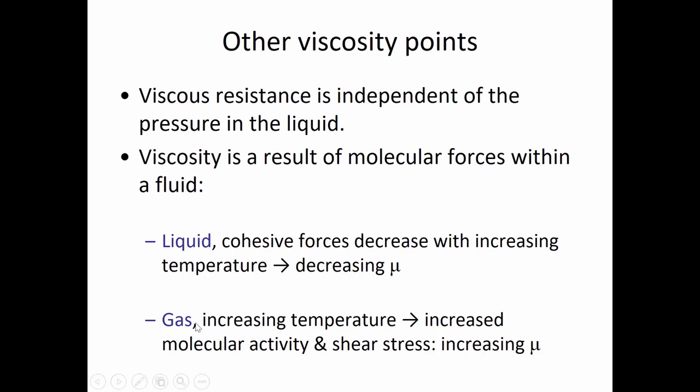In the case of a gas, because the molecules are bumping into each other, they have a lot more collisions, and the velocity of those collisions is higher. The gas molecules are getting in the way slightly more, and so the viscous resistance is greater as the temperature goes up.